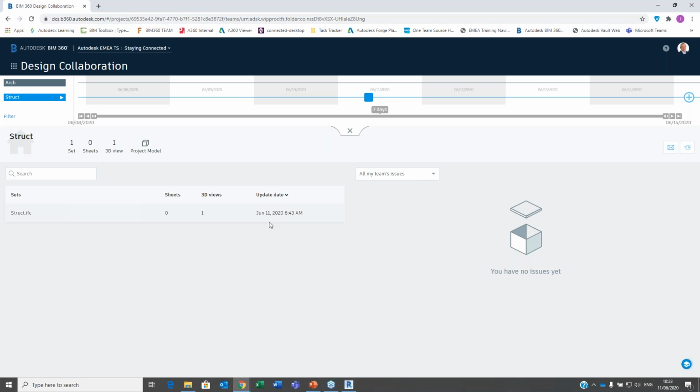So let's go into BIM 360 design. Okay, so what you'll see here is the design module. So remember, we've got the Revit interface, we've got docs, and we've got this sort of, I'm going to call it a filter, which is the design collaboration module in the cloud. And what you'll see here immediately is a timeline. So that safe to central publishing packaging is something that is actually explicitly there in the timeline.